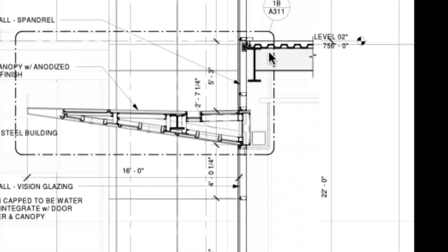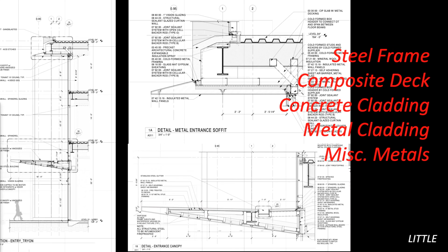So we can see the typical components of the steel frame. Because this is our larger member and these are our smaller members, we will have these more regularly. We want to begin to build up a grid work of these secondary members at 8 to 10 foot spacing, because that is a really good spanning distance for this next system. So major member, secondary member, and then these little devices, the composite floor, spanning the other way. I really do like this though, because it shows quite a few things happening that are interesting.